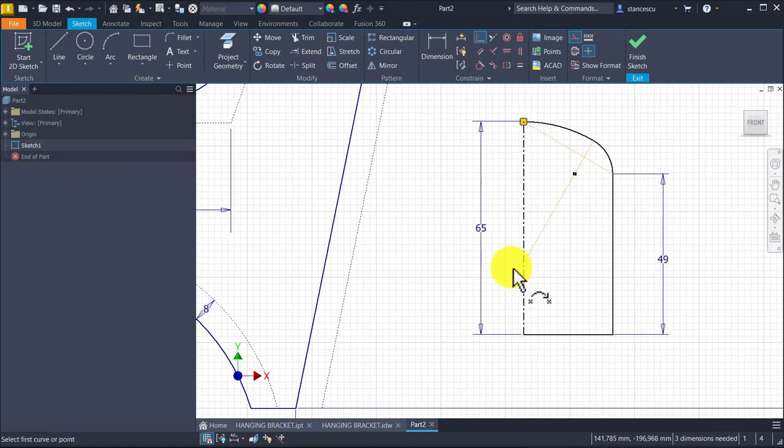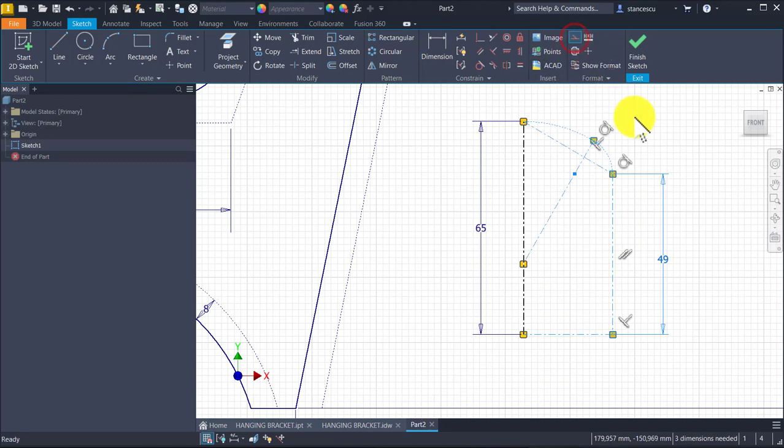Now we have on this line the 2 points, which means that here is tangency. Yes, between these two is a tangent constraint. Okay, this is only for the future. We'll use it. All lines will be construction lines.